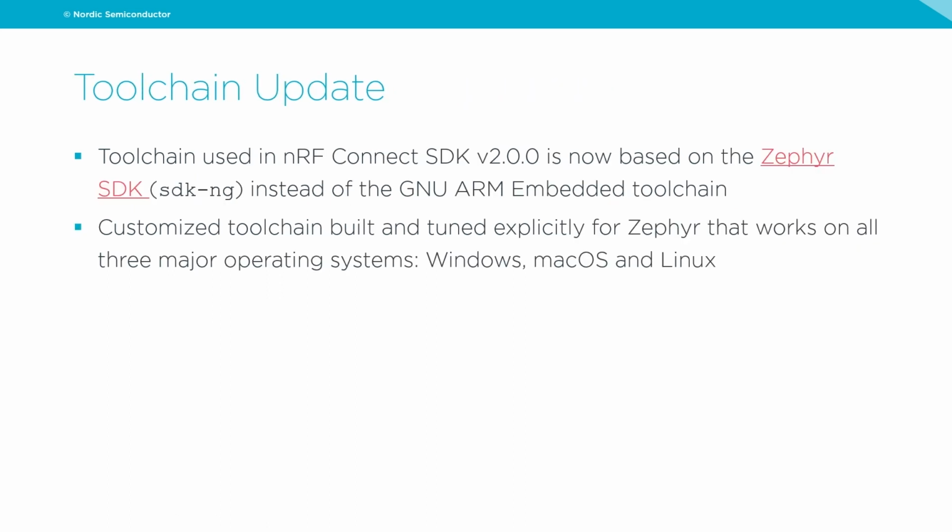Now, another update, the toolchain used in the nRF Connect SDK 2.0.0 is now based on the Zephyr SDK. So that's the name of the toolchain of Zephyr, instead of the GNU ARM embedded toolchain. And the goal here is to have a customized toolchain built and tuned explicitly for the Zephyr RTOS, which is kind of like what our SDK is based on internally.